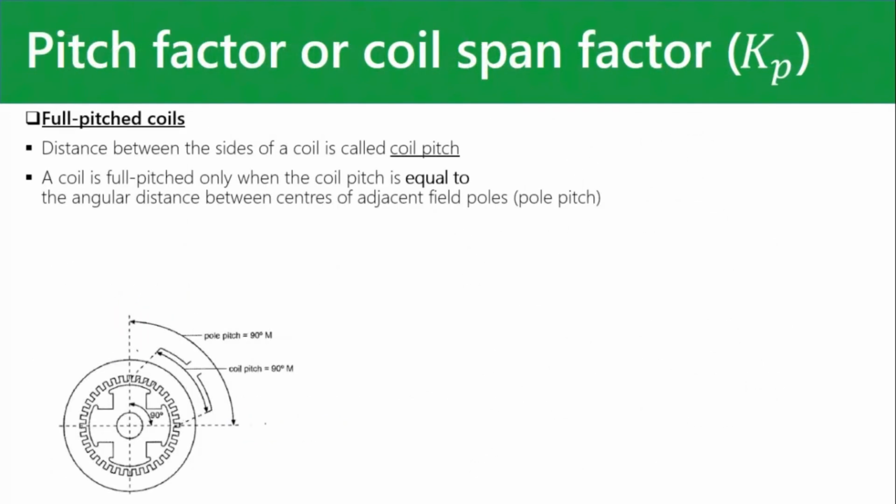All right, so now remember we had those 2 constants at the end of our EMF equation, eh? E per phase. What did we have? Okay, you had 4 f Φ × turns per phase × form factor. Then you had 2 K_p K_d, these two at the end. Right, what is K_p? I'll show you now. It's called the pitch factor.